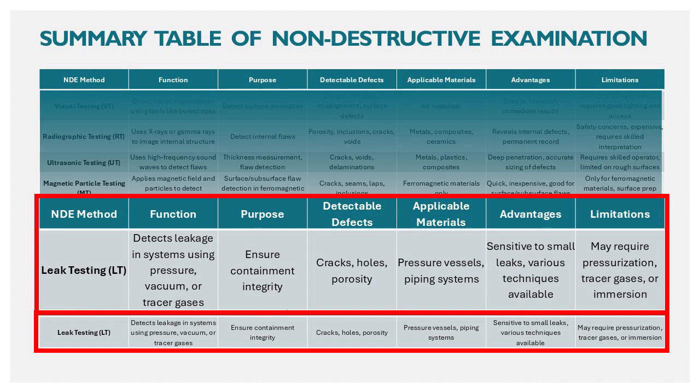The advantages of leak testing include sensitivity to small leaks and multiple techniques available, such as bubble, pressure decay, and helium. The limitations of leak testing include that it may require pressurization or immersion, setup can be complex, and environmental factors may affect results.